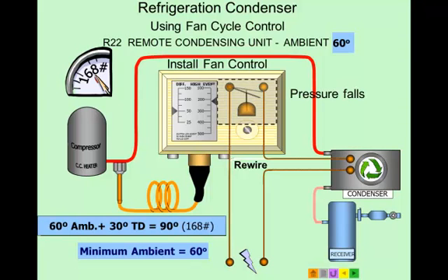If the pressure falls, as it will under low ambient conditions, notice the switch will open and the fan would stop. Once the fan stops, there is no more air across the condenser, the pressure will rise and the switch will close and bring the fan back on.